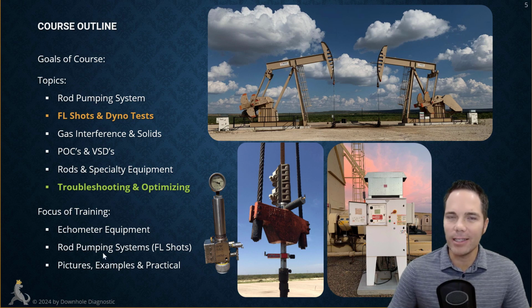So we're going to focus on rod pumping systems in this course. You might have got that hint from the name of the course, but I realize that some people are probably coming to this course because they're really just interested in fluid level shots. So the fluid level gun, you can take a fluid level shot essentially down any type of well. As long as there's not fluid to surface on both sides, you can shoot down either the tubing or the casing.